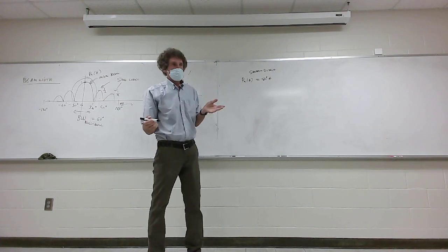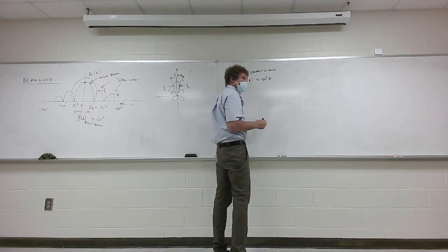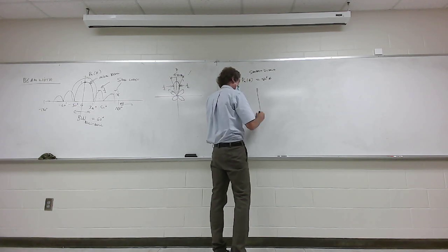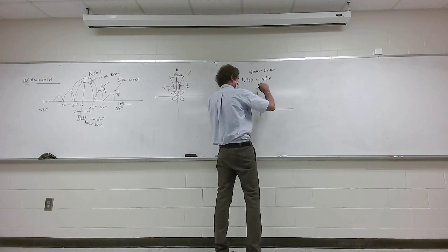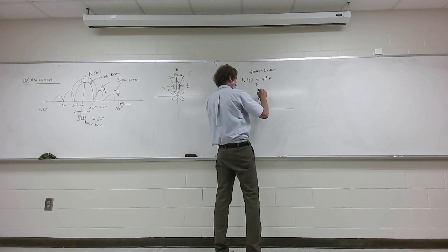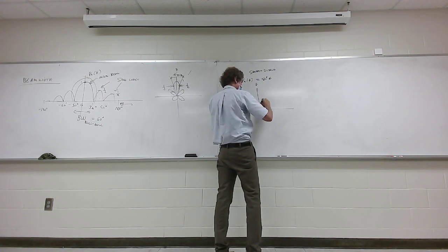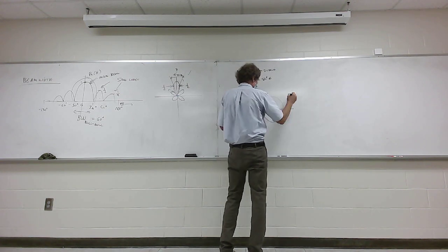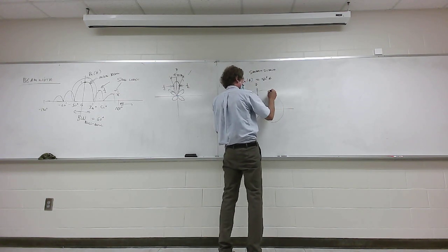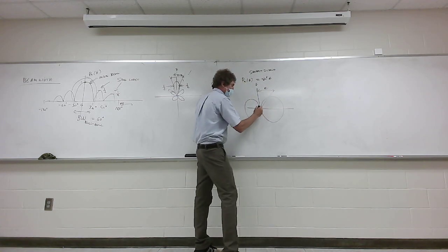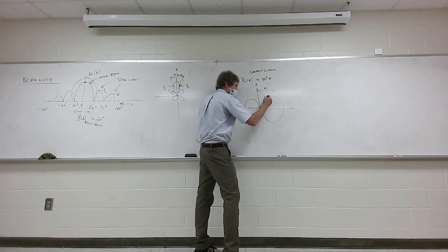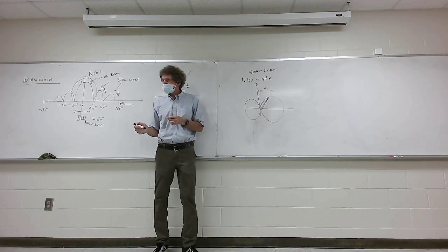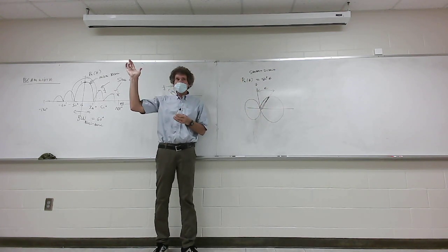If we take a look at the beam width of this, I'm going to plot it in polar coordinates. So this would be the z-axis, this would be the angle. It would look like this. Again, this is the measurement theta, and this is the actual length of the range vector r. Y'all follow me? That would be sine squared. How many understand what I've done there? With me? All right, what's the beam width of that?